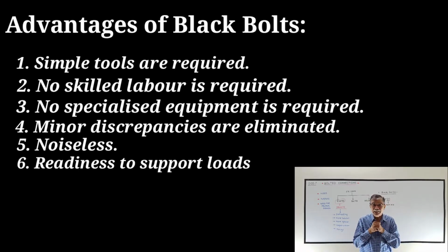Sixth advantage is readiness to support loads. In case of riveting, as it is heated to red hot, you have to wait till it cools. This is not the case in bolting. As soon as you have tightened all washers and nuts, the structure is ready to support loads. Okay? The next advantage is speedy in construction.